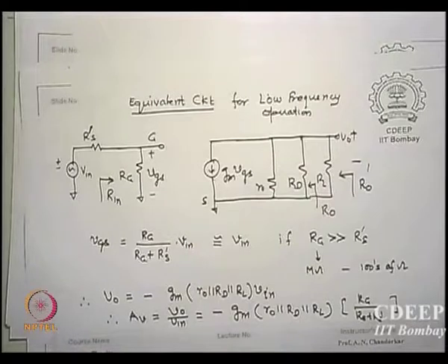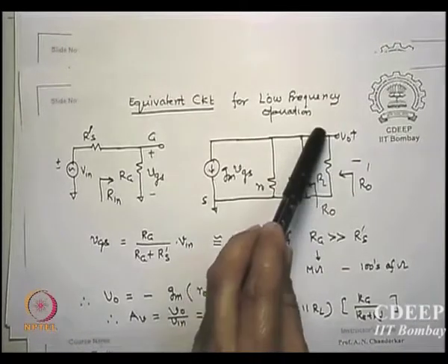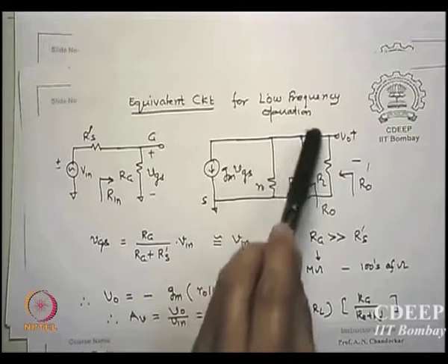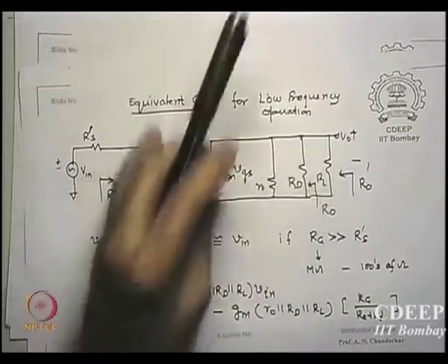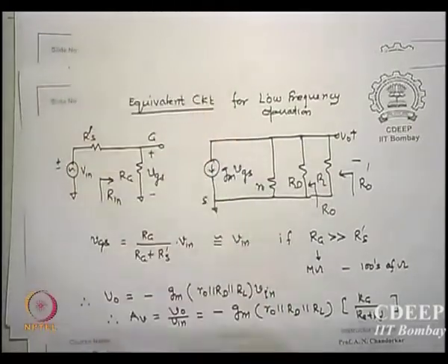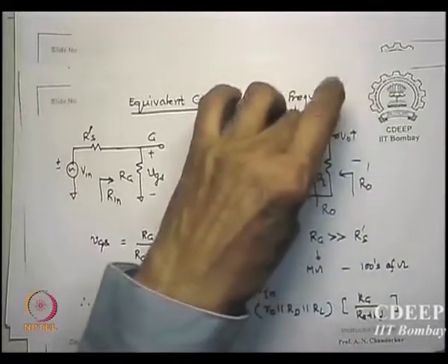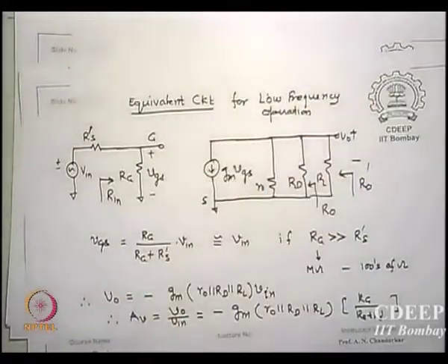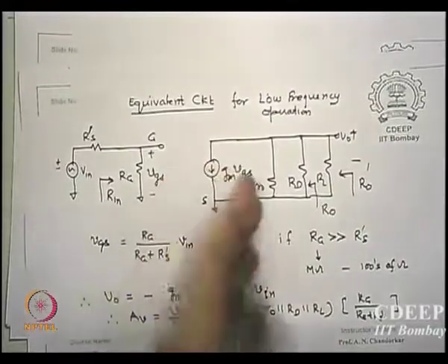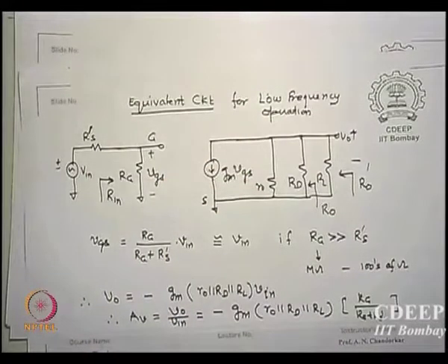If you see a resistance coming from the outside and if I put a voltage source and find the current, V by I, this is the current, this I am opening. So if I put a V0 and there are two paths, that means parallel, so V0 by I is the parallel combination of R0 parallel RD. So the output resistance is R0 parallel RD.